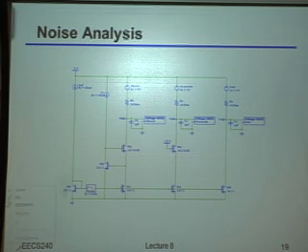So let me start this out by taking a quick poll. Let me number each of these things one at a time. Number 1 is just your standard, regular current source. 2 is your cascoded current source. And 3 is a gain-boosted cascoded current source. It looks a little bit funny, but if you deconvolve this a little bit, this thing here is really just an amplifier, right? It's a common source amplifier. Notice it's looking at the source voltage. Its output is driving the gate of that cascode. It's really just a gain-boosted cascode.